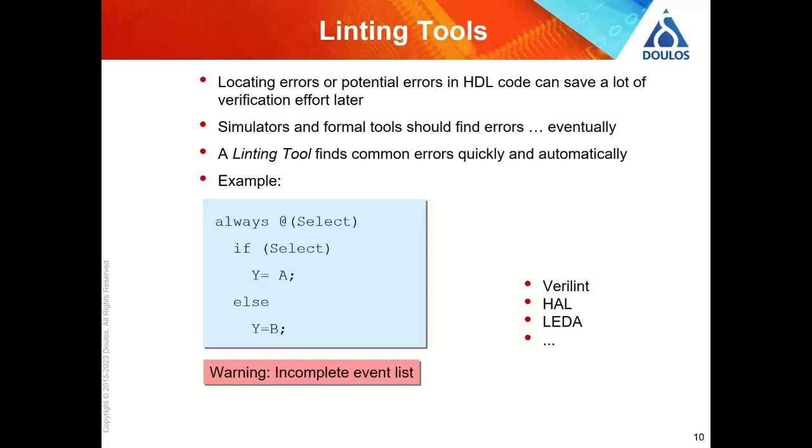Verilog doesn't take that approach at all, and neither does SystemVerilog. So they are much more flexible, which can make the code easier to write, but you have a problem where you can write code that compiles, which is functionally incorrect. Okay, so that takes experience to understand and to do it correctly.